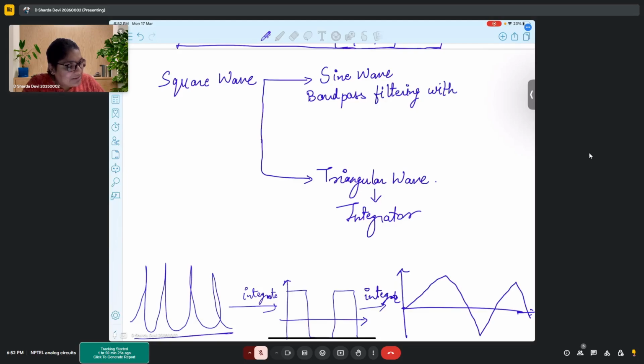with high Q. High Q basically means high selectivity. Q is nothing but selectivity. Very high selectivity. We discussed the notch filter, remember? The band stop filter, where it only rejects a single frequency, we called that particular filter a notch filter.